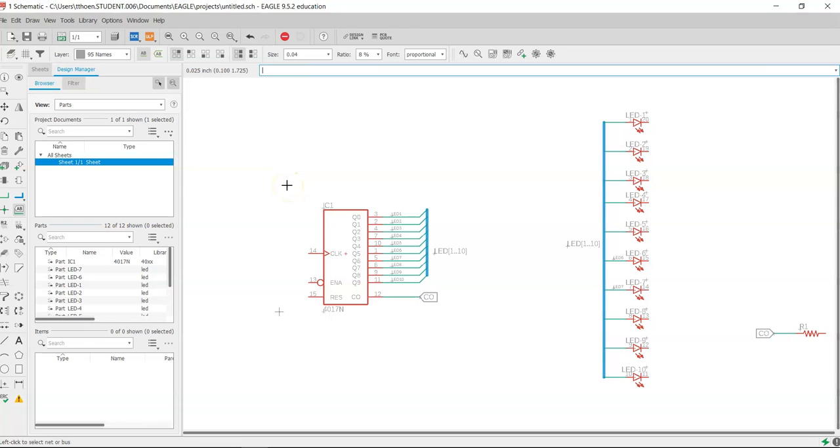Now, when you get to the assignment this week where you're going to be adding the microcontroller part to your lab, you're going to be doing this. You're going to be adding these labels, and you're going to be adding buses. When you do this, please use the exact same naming convention as I have. So, for example, we have alarm out, hour set. We have 7 segment, 0 through 3, etc.